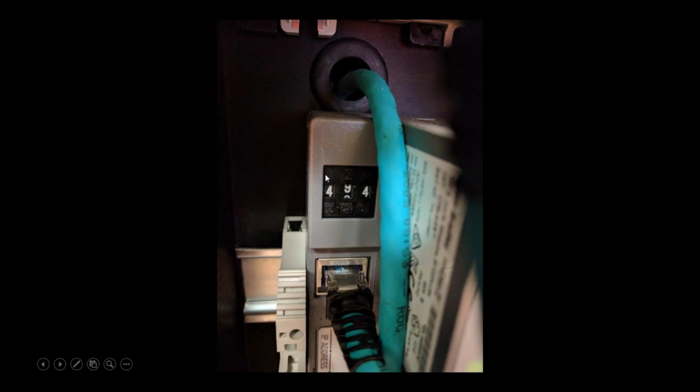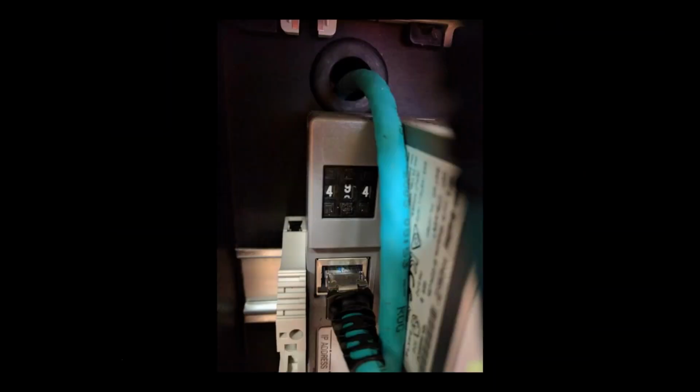But if you try to set the Ethernet address and this thumb wheel is still between 0 and 255, you're going to have issues and you're never going to be able to reset it. Another thing to note is on the side, right over here on this long thing down below. Plus I give you a way to write the IP address, so when you're in the field you can write it. But on the side down below, you will see something called the Ethernet